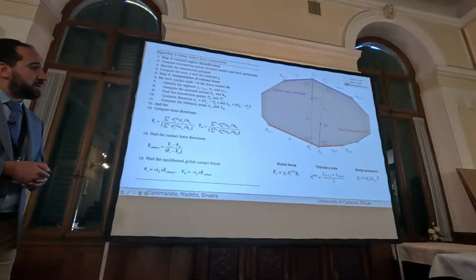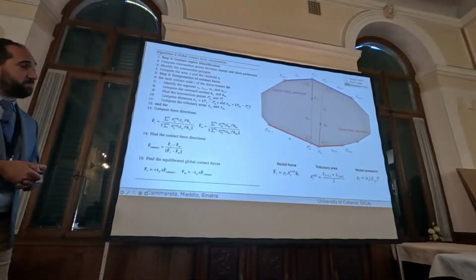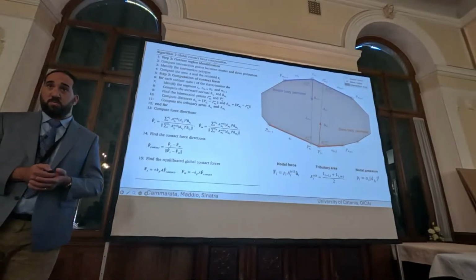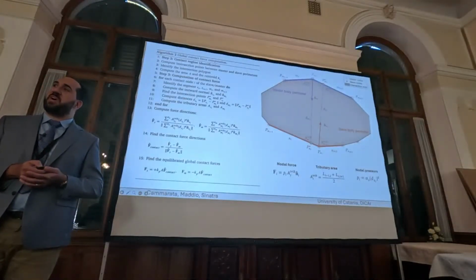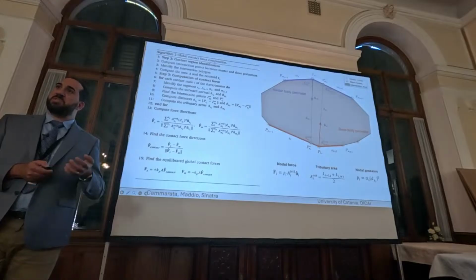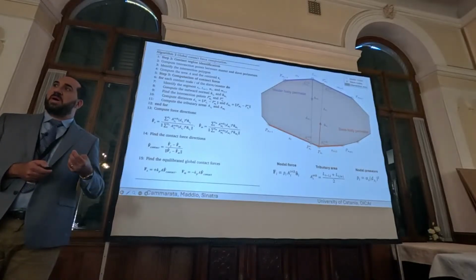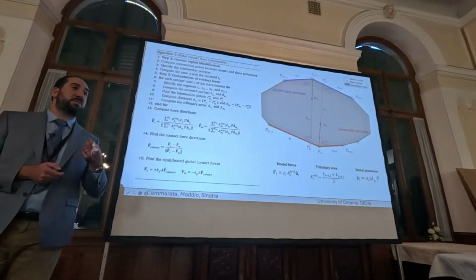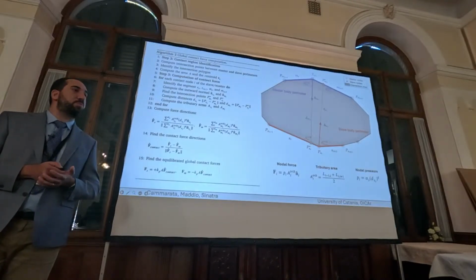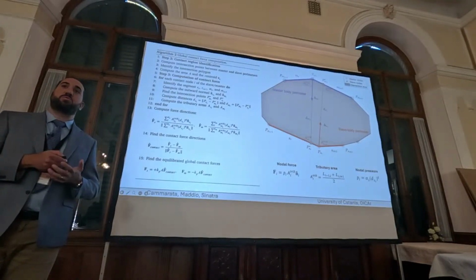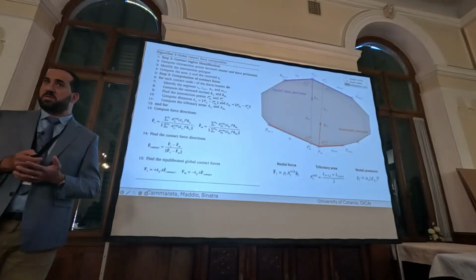And this distance is raised to the power Q, where we discovered that Q must be 2 in order to satisfy Hertzian contact. But we discovered also that Q can assume other values in order to, for example, adapt the method to non-conformal profiles.